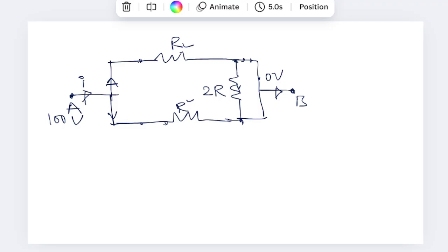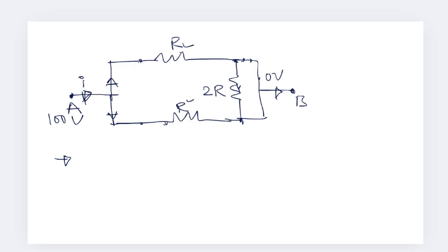You have to consider 2 points. The first one is the current: is the current in the circuit the same or not? Suppose the current enters from A and exits from the point B. Here the current is dividing, so you have to observe carefully: I1 and I2. The current is dividing, which is one of the conditions for parallel resistance.